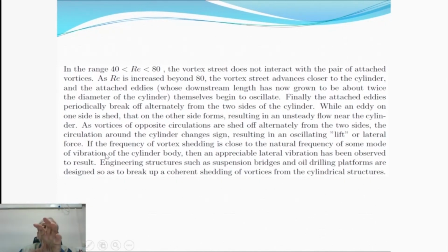Usually, if we imagine flow around a cylinder and the flow is perfectly symmetrical, we are not supposed to get any lift. But here we can clearly see that the circulation around the cylinder changes sign, and then it develops positive lift and negative lift periodically.